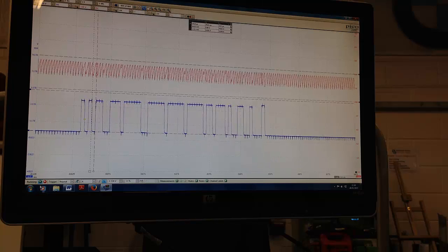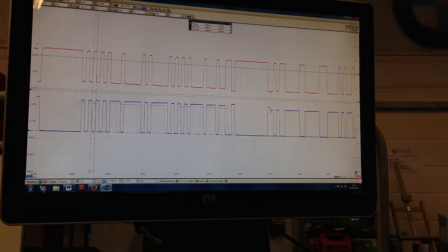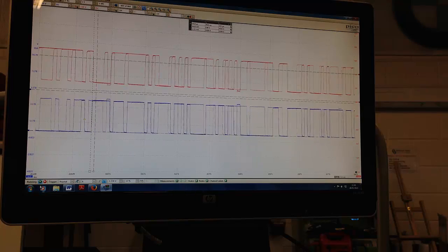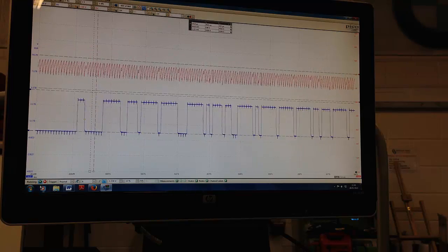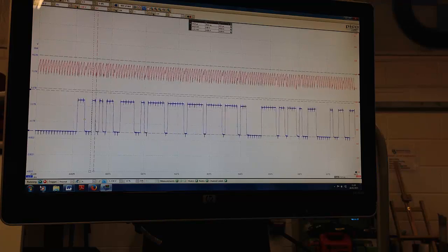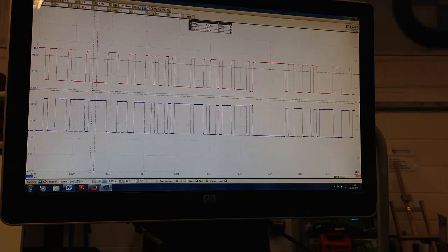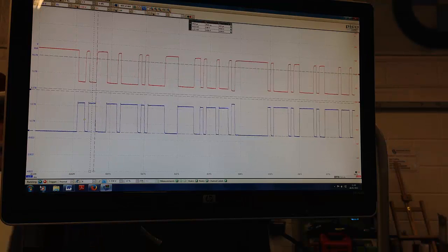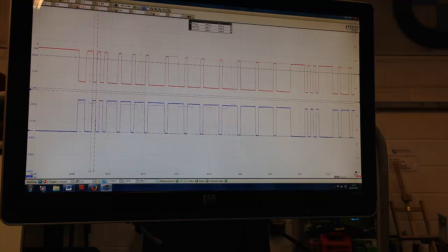So it looks like then that unit could be shorting. There we go, we can hear the wipers running on the screen now. As I disconnect that and reconnect it, some of the functions are partly returning. Okay, very interesting. Now, let's have a think about why that could be.